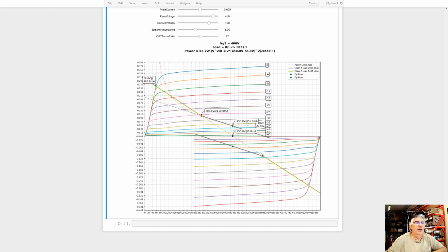And then down here, when the voltage is really negative, the bottom tube is carrying all the current. But in the middle, both tubes are carrying the current. And so effectively, the load line is a straight line, even though there's this discontinuity that occurs on both the individual tubes. All right, I hope that makes sense.